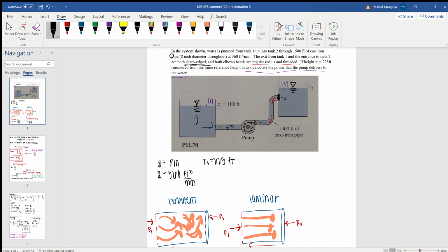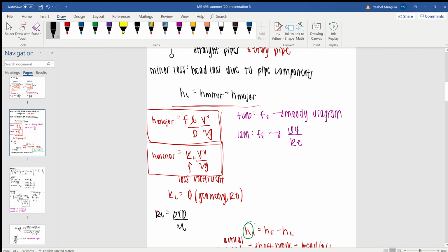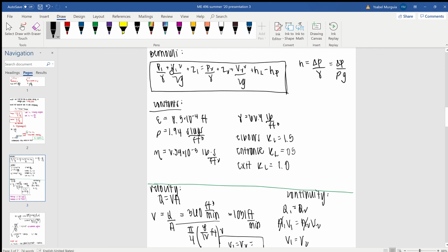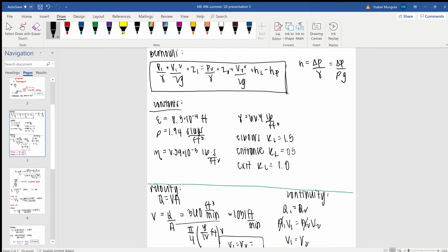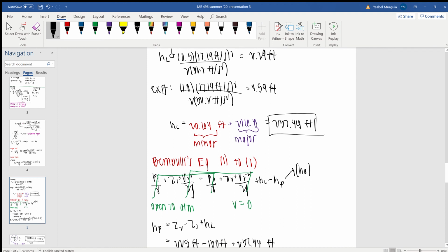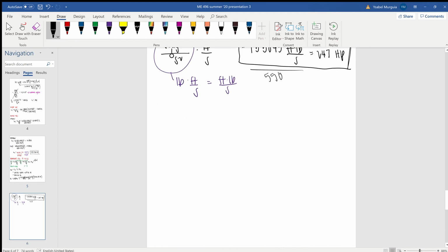That's about it. We just summarized. Initially, I summarized through the basic concepts of all of this pipe flow. And then we went through the minor losses and the head losses. Bernoulli's equation was modified a bit to accommodate for the turbo machine, aka the pump, which is a centrifugal pump. And then we just went through and solved. Calculating my units, I was able to correctly see that I solved for the correct unit at least. Hopefully the answer is right.